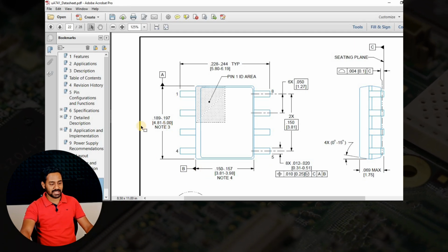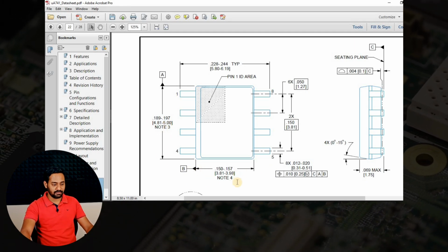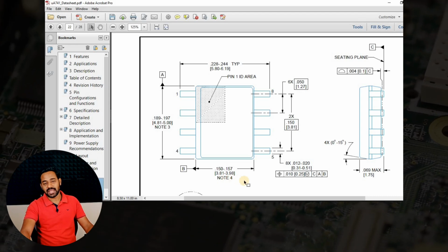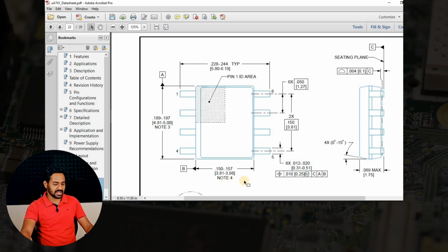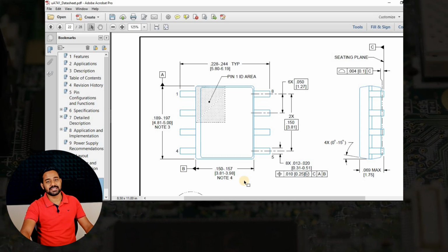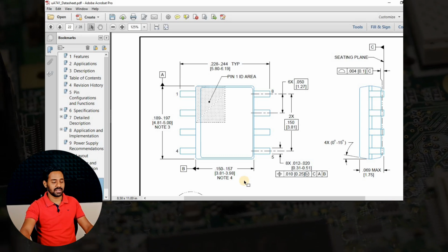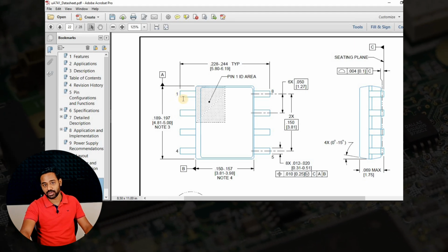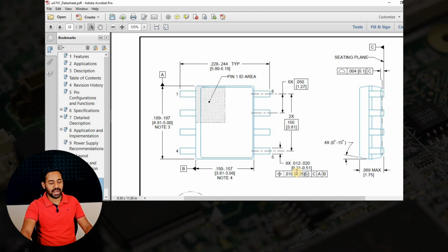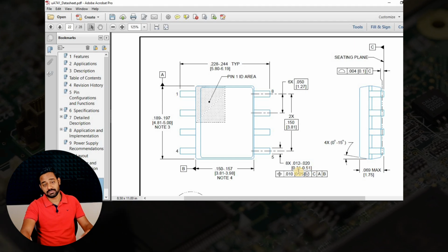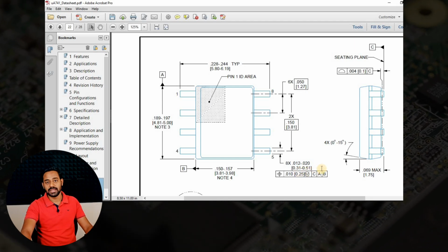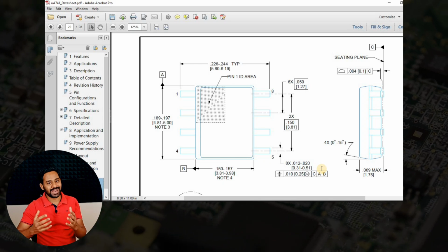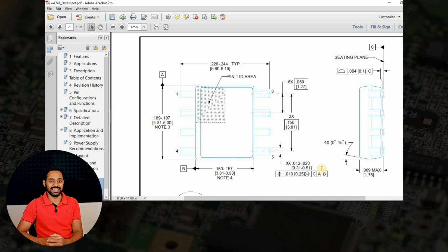And then the width of the IC is going to be 3.81 to 3.98. I would like to consider somewhere around 3.7 so that it is easy for us to create a border. But again, it totally depends on how long the width of the pad you are going to consider. Having a height of the pad as 0.312, 0.51. With these details, we are going to start designing the schematic symbol and PCB footprint using EasyEDA.